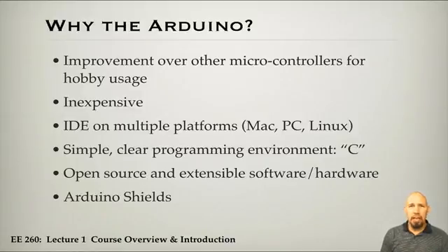It can be something like communication. We're going to use a communication library that allows you to communicate serially from the Arduino to the computer console, so you can actually get a display readout. We're going to use a stepper motor library that allows you to control stepper motors. Stepper motors are pretty complicated. There's a lot of sequencing associated with the control of a stepper motor, but it's going to be invisible to you because it's just there.